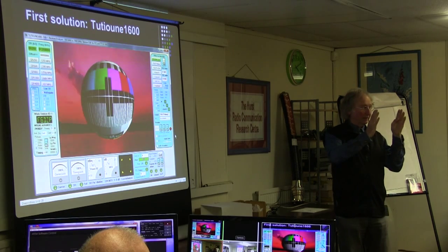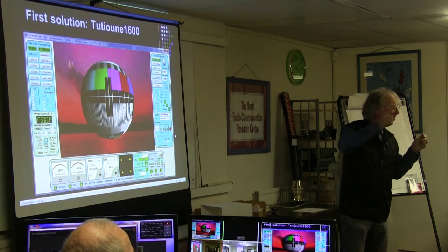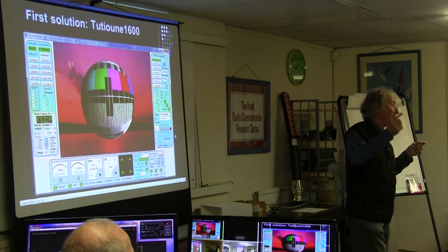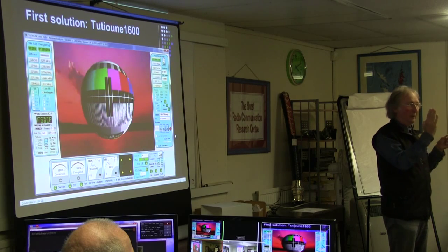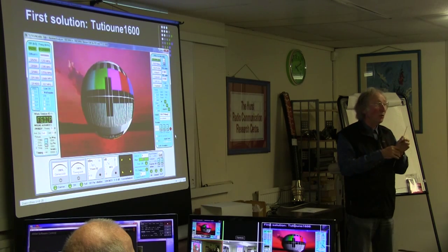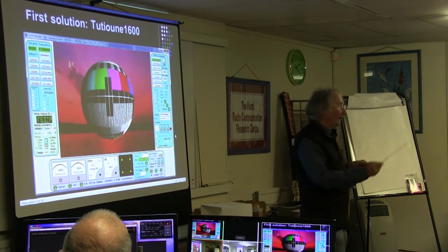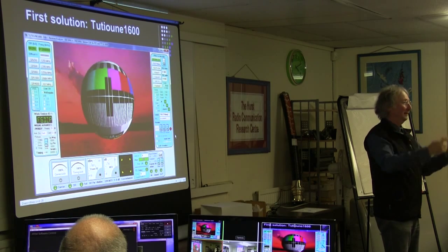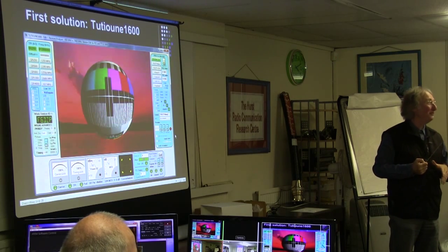So it is easier for the demodulator, for the PLL of the symbol rate, of the timing lock on the symbol rate, it is easier for it to find the rate of the phase modulation, but it is more difficult to find the center of the frequency, because your shape is not a very beautiful shape, as we have seen at the output of the DigiFin.